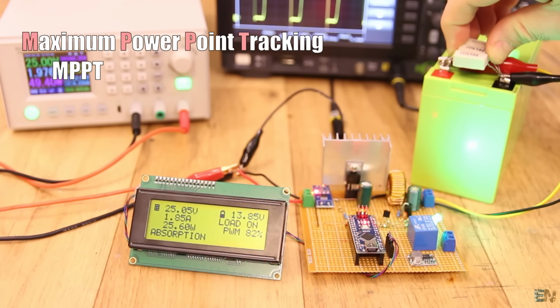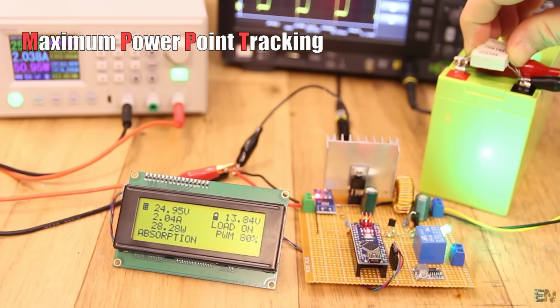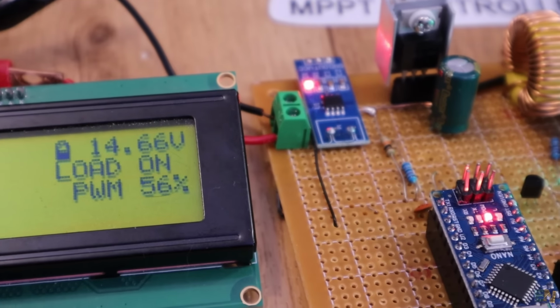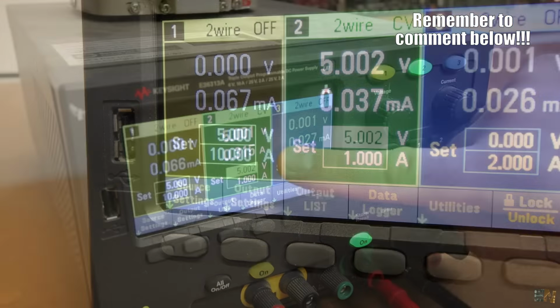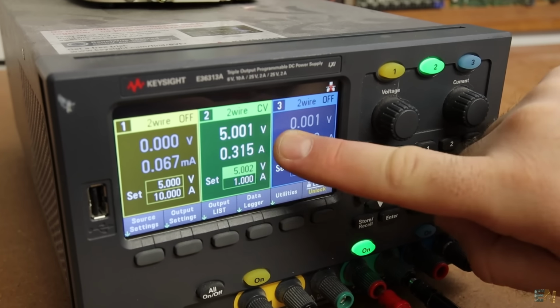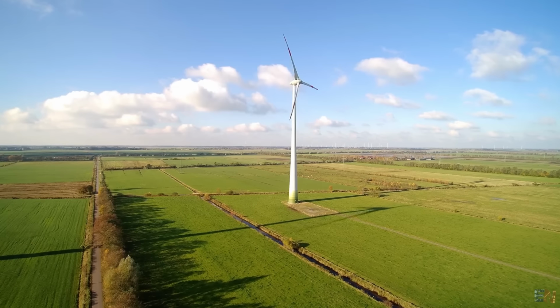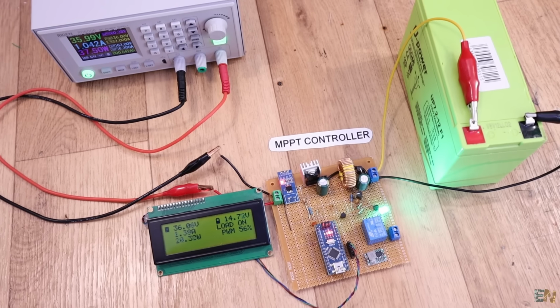Now MPPT, like this project here from a previous video, stands for Maximum Power Point Tracking. So basically this device will track the power output of a variable power source. It has to be variable because if it were a power supply like the one I have here in my workshop, which can give a steady output of voltage and current, you wouldn't need an MPPT. We use this device with variable power sources such as a solar panel, maybe a wind turbine, and who knows what kind of generator that has a variable output of voltage and current.